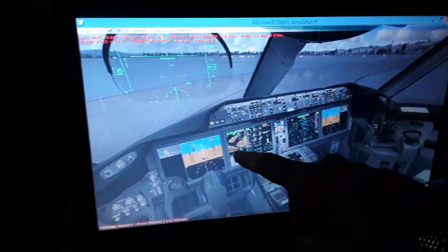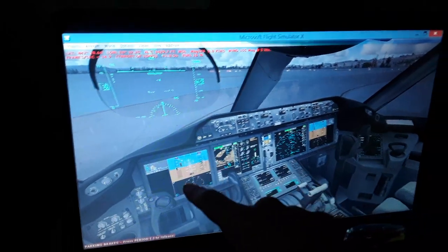We have also the navigation aids, the nav aids, the workstations, ADFs and DMEs, the waypoints which are horizontal and vertical navigation fixes, and altitude and airspeed constraints. We have to fly through some waypoints, as I already explained to you. Using the flight management computer, we're gonna create a flight plan. Later, you're gonna see the purple or magenta line of the flight plan from the flight management computer is gonna be displayed in the navigation display in the HSI.